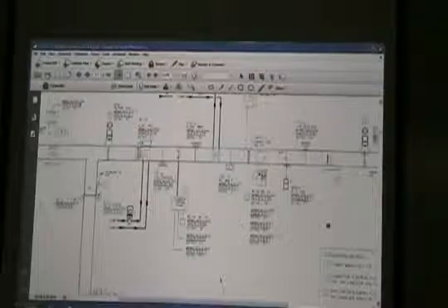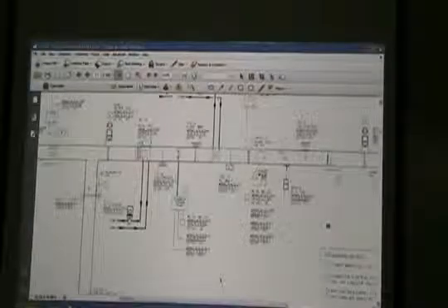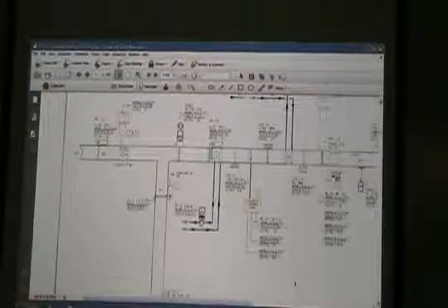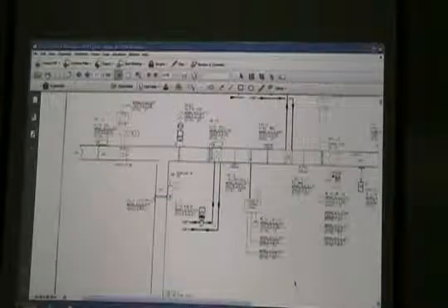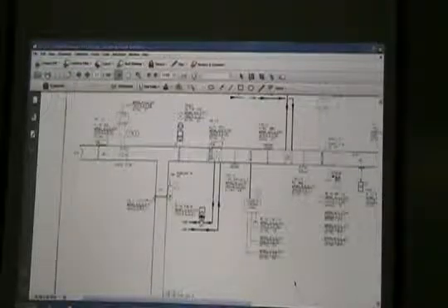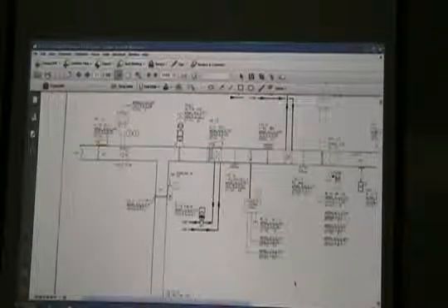Outside air. So there's our outside air flow measuring station. There's our outside air damper. We got a signal here that's probably an analog input into our controller, or actually, that's sensing into the controller, and then we're going to control this damper. So the fan opens this damper when it starts, or the system opens the damper when the fan starts. But then we've got a separate actuator here so that we can take control of this damper and always maintain, they specify, here it is right here, 4,900 CFM